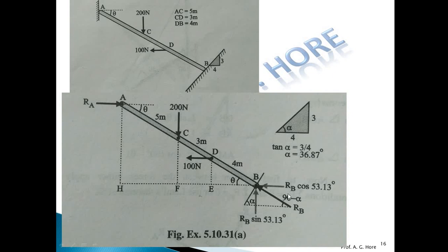Okay. Then RB, which is inclined, this having 90 minus alpha is this one. So this is an inclined force, so make its components, a horizontal and vertical component of that RB. This is a second quadrant force, so minus, it goes left and one component goes upward. Now count the number of forces. 1, 2, 3, 4 forces, not concurrent forces.